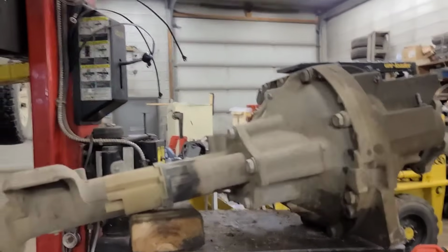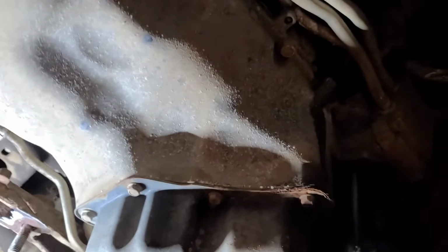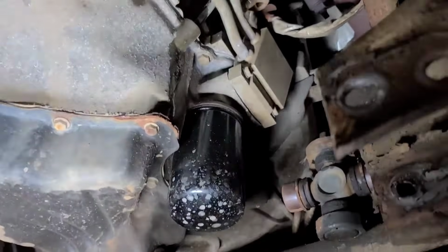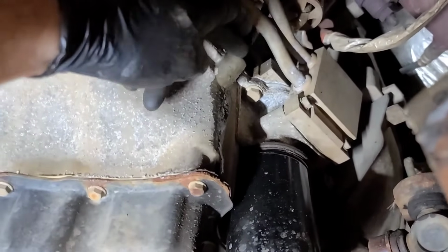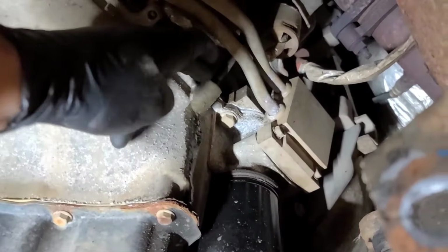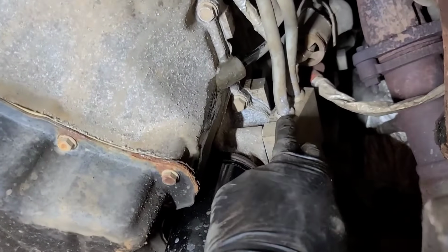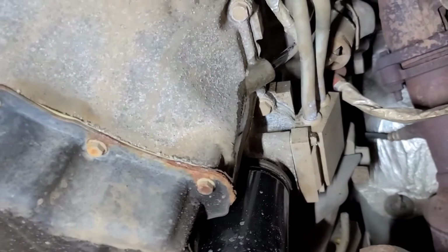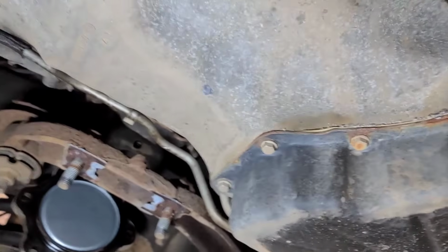So there's the front diff out of the truck. I might as well leave it on the jack stand because there's no need to take it off. Now you can see there's a little bit more room to get at the oil pan. Just looking underneath here, I see there's an engine oil dipstick tube going into the pan. Thanks GM. So that means there's a fastener up top, and I sprayed some penetrating fluid on it already. The oil cooler is attached to the pan. Cooler lines are clipped to the side of the engine.